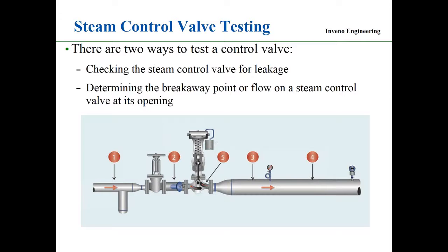Now, if you're just heating water to 80 degrees C, and you can take 5 plus or minus 5 degrees C fluctuation, it's not a problem. But we get in processes where you have to have plus or minus 0.5 degrees C. So this breakaway point inside this control valve becomes very, very important. So there's a couple things that we do on the control valves: setting up this control valve for the breakaway point and understanding the breakaway point in the valve, and that's setting up the control valve.